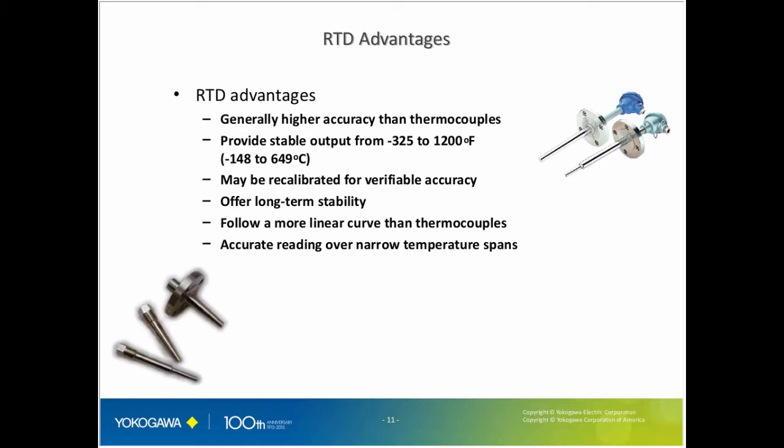So this is kind of two different ways. They can either be calibrated, just a verification to say, okay, my RTD is within tolerance, but they also can be recalibrated, so provided a new characterization to establish a new resistance versus temperature curve fit. We'll discuss this in a later slide, that sensor matching that I mentioned in our intro. We'll discuss that a little bit more later on.